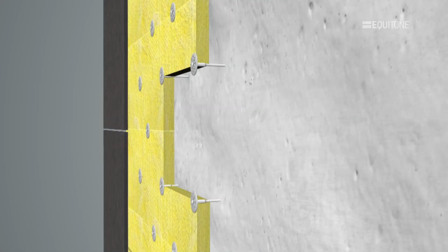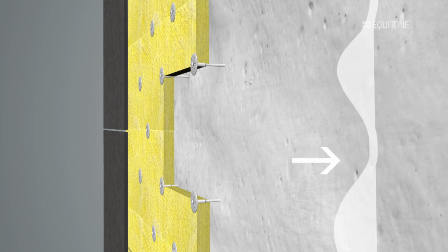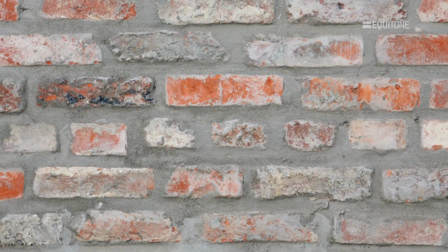The position of the panel is determined by adding the thickness of insulation to the cavity width and allowing a little extra as a tolerance for uneven walls. Whichever subconstruction is used, the wall should be checked by the installer prior to installation to confirm that it is flat and to ensure that the correct fixing and details are used.